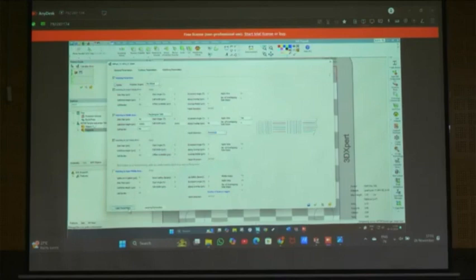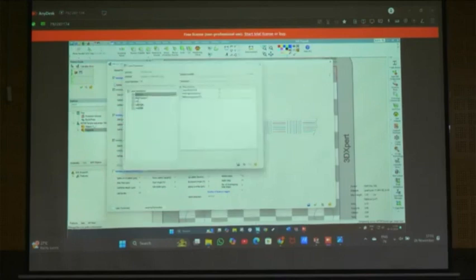Yeah, laser parameters you can change here. Part, right, yeah, part. 100 watts it is there, you can keep it at 90 watts also. And 1200 mm per second, these are the default parameters we are using here. And if you want to keep 600 or 1000, you can do that also here.